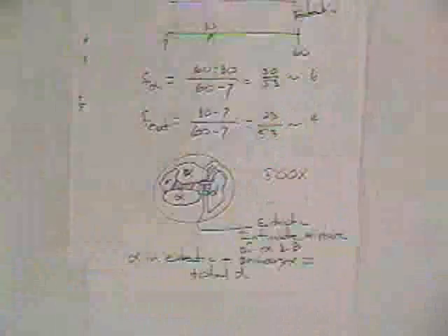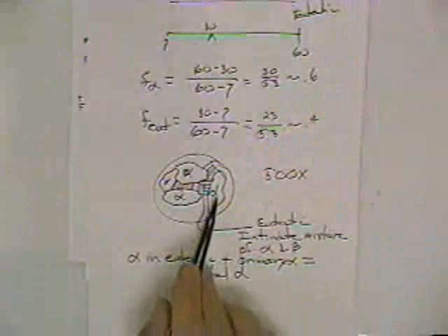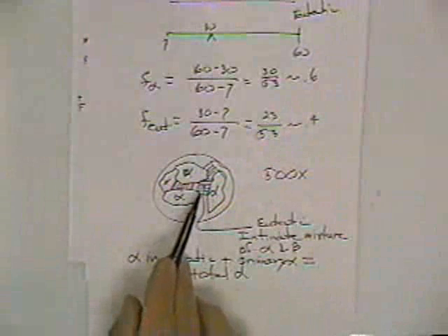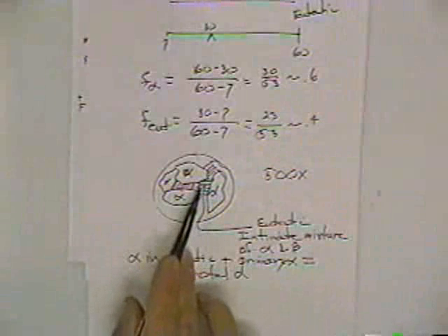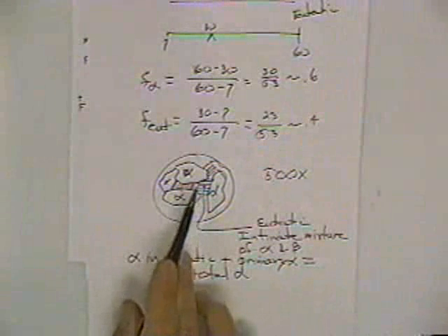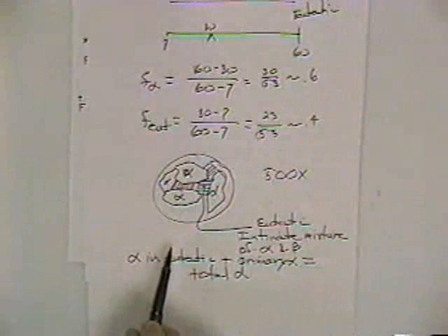So I really ought to put this thing back up here and cross this diagram off, and remind you that you would have primary alpha, and then this crosshatch region represents a mixture of alpha and beta. Well, I hope that gives you a little bit of an idea how to make some lever rule calculations and how to determine the compositions.